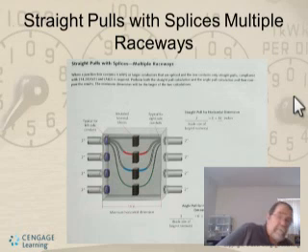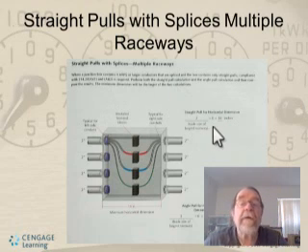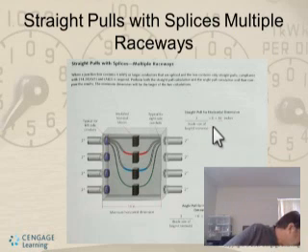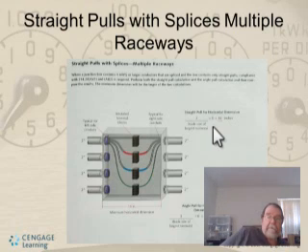So essentially, here we're showing the calculation for the horizontal, which is your X dimension, and then your vertical. There you see the angle pull for horizontal is 18 inches, which is behind my picture, and then the vertical is the one at the top, which is 16 inches. And basically, all the conduits going in are 2-inch conduit. So you use a designator of 8 to 16. Here you're not using the 6 designator, you're using the 8 because they're all the same.